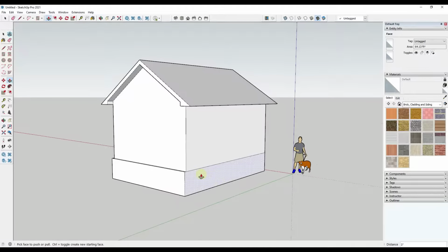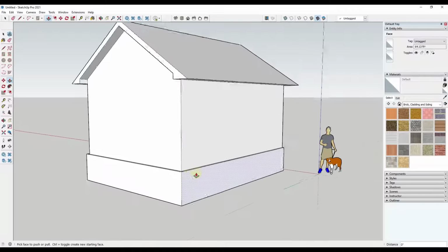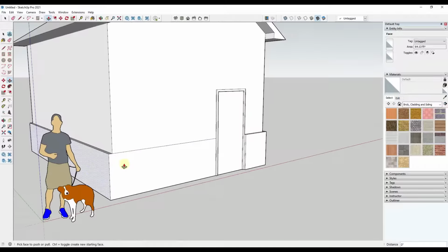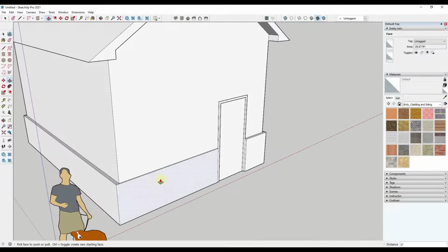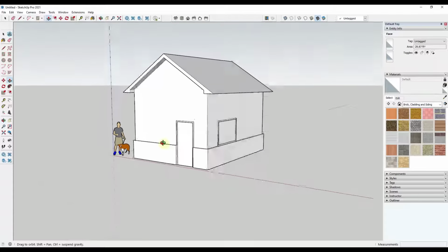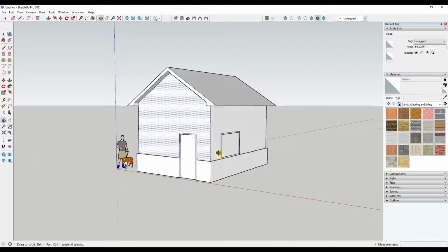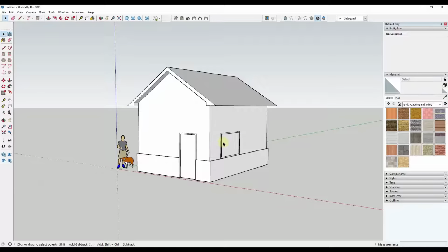And then I can come over here and just double click in order to do that again, because this tool retains the last distance that you entered for it. So you can just come in here and double click to really quickly do this, but we're running into our wall frame again. So we're just going to do 2 more inches and call it good. So now we have a house with a brick wainscot down below. We've got a roof, we've got doors and windows.